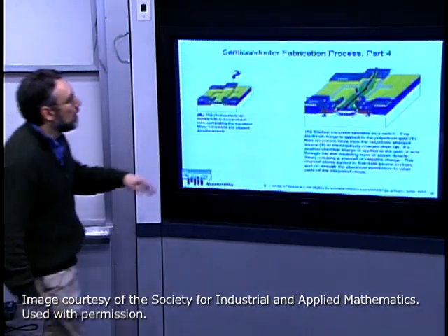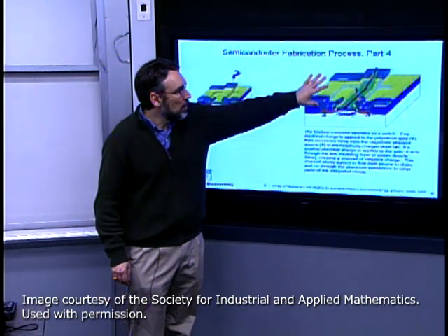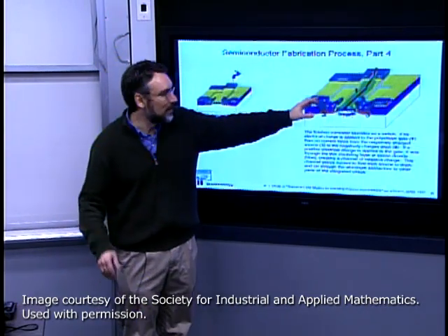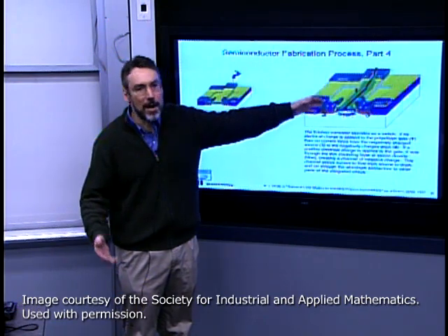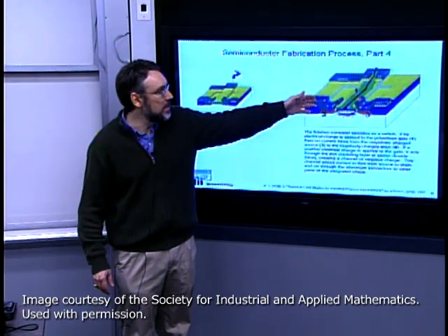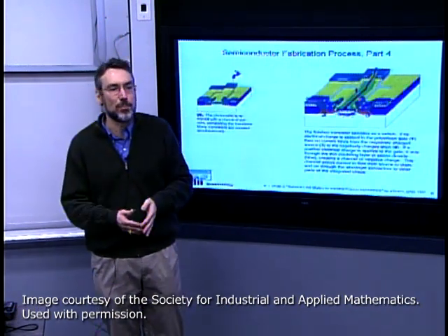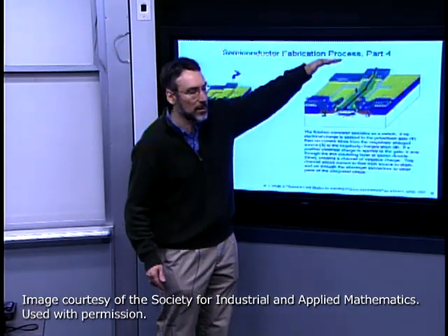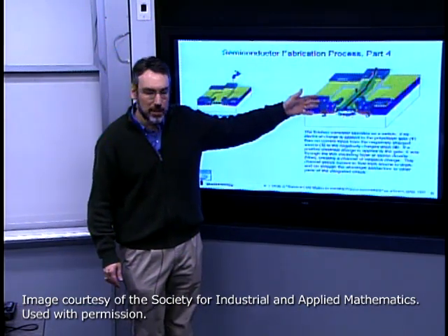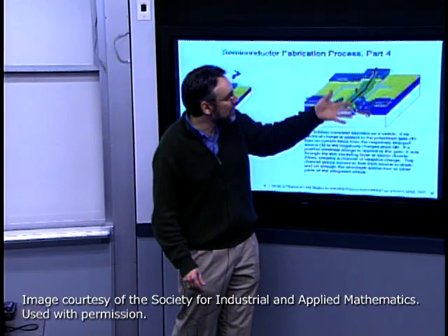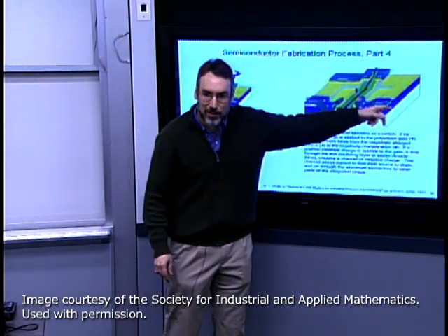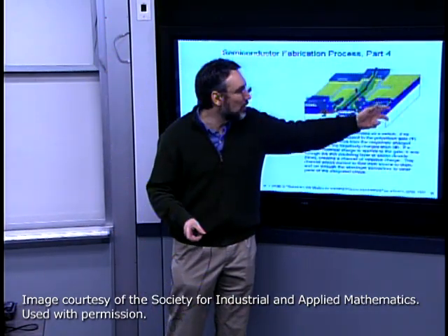Now this is a single level metal, very simple transistor in building up a several billion transistor chip, or even 100 transistor chip. We now need to also electrically interconnect all of those devices. And there's a whole additional sequence of process steps that are used to build multiple levels of metal contact. But conceptually, they're very similar to those that we've seen so far. Here I've got access to this individual transistor. Clearly, laterally, I can have neighboring transistors that I've wired together with the patterned aluminum.